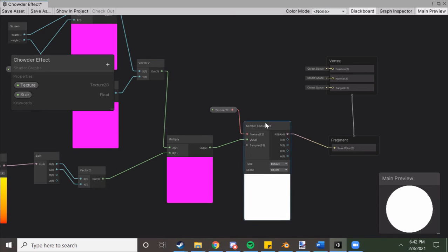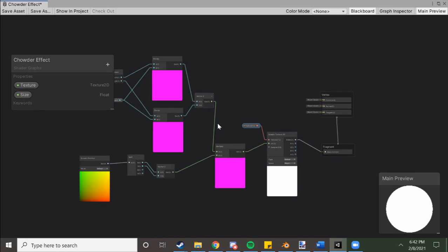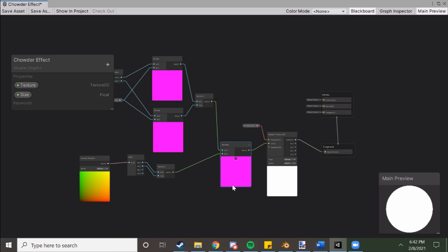And then you use the texture that you have and put that onto the base color. This is an unlit material, but you can do this with lit materials, same idea. The reason I'm showing this off is because there's a lot of cool tricks you can do with shaders to texture objects. This is just one. If you wanted your UVs to be in world space, like the grass in Animal Crossing or the paths in that game, they use world space for the UVs because it's a large repeating texture.